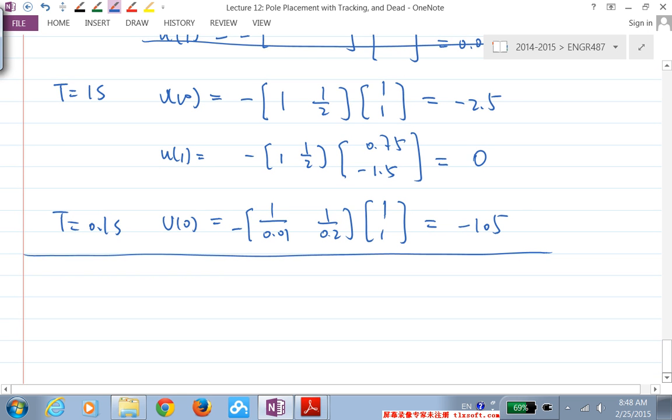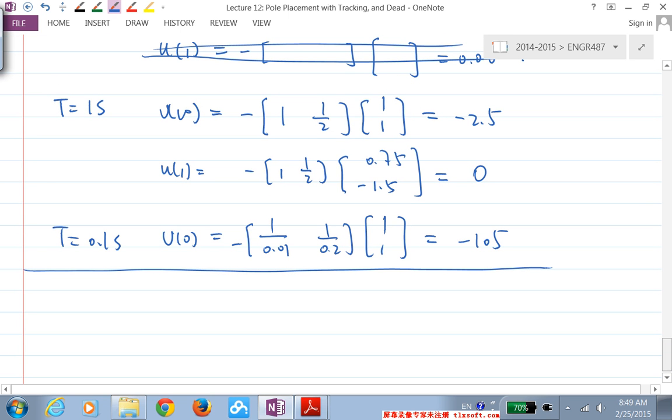In the lab visit, you can see how easy it is to implement a pole placement control. You can try it out yourself, but you do need a little bit more knowledge on how to pick the poles. The poles you pick need to satisfy certain time response specifications. You can't choose them arbitrarily; poles correspond to a certain set of responses that you are looking for.